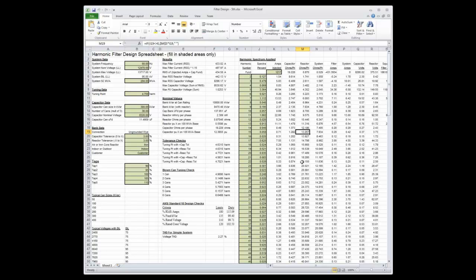So you may right out of the gate say, oh, I need X amount of power factor correction. And that's good, but you need to perform simulations and do frequency scans with that design hooked onto the bus to make sure you're not sitting at an integer harmonic for almost all of your normal conditions.